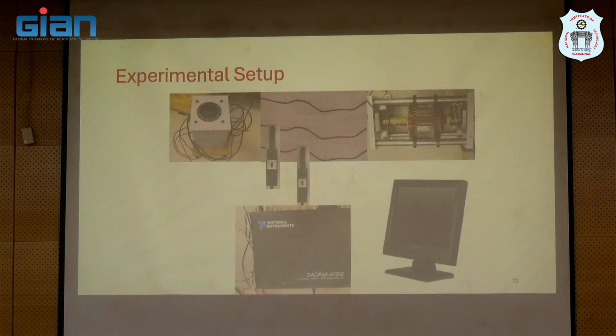If you are in NITs or IITs, you will have access to all these tools. But if you are in another institution, you may or may not have access to these tools. You don't necessarily need such expensive equipment is what I'm trying to say. Exactly. Most of the modern oscilloscopes already have digital storage capability. The only thing you may have to check is the resolution of those oscilloscopes' ADC system. If they are 8-bit resolution, it might work out, it might not work out. So you have to try it out, depending upon the voltage and current signals you are working with, okay?